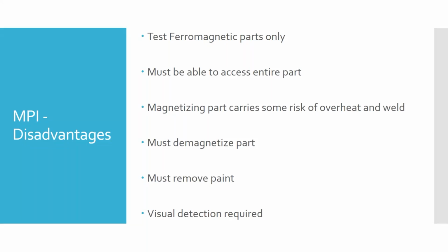What do you think a magnetic part on an airplane might do? It throws off the avionics and navigation equipment. In fact, when an airplane gets hit by lightning, steel parts can be magnetized. We'll use a Gauss gauge to check the magnetism on the parts we're testing. But when we were working on aircraft that got hit by lightning, we'd have to go around with the same Gauss gauge and figure out if anything on the airplane got magnetized. And then if it did, we'd have to demagnetize it. The big culprits were landing gear.